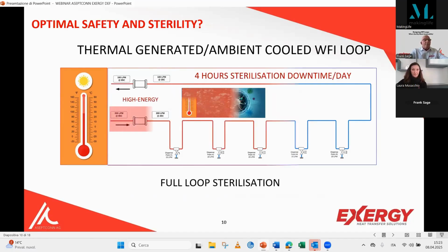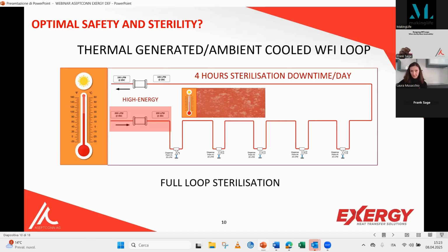So sterility is a very, very real concern on an ambient WFI distribution and dispense design, with hidden costs, increased vigilance, and regular calibration of instrumentation needed to comply with regulatory GMP standards.